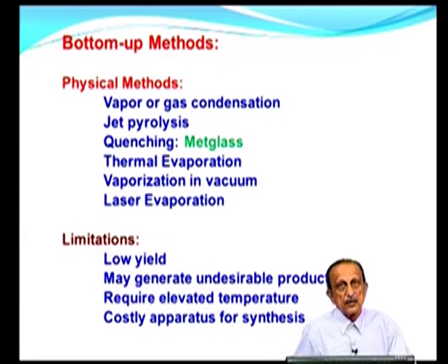And if you do not allow that condensation to take place over a relatively long period of time, that is, if you quench it, then in the absence of time for these atoms in this condensate to relax into crystallographic positions, proper positions, you often get either nanocrystals, very small crystals, or you get amorphous material.